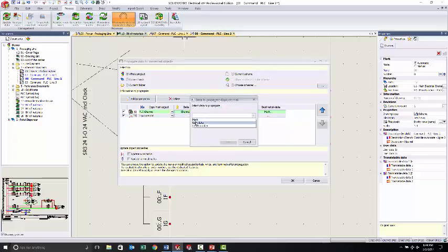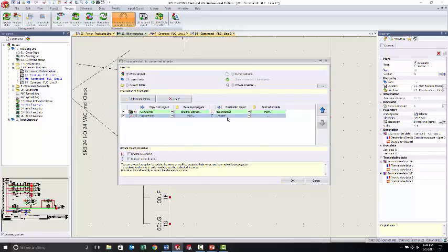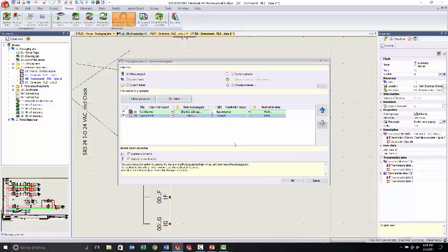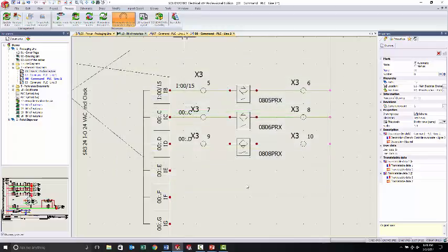So taking that mark, I can now push that directly to, because of course terminal is the only selection I can do at this point. And I can do the same. I don't want mark, I want mark. Voice commands don't work. Yeah, one of these days they will. And again, I can hit OK, and now it will actually push that wire number to the terminal.